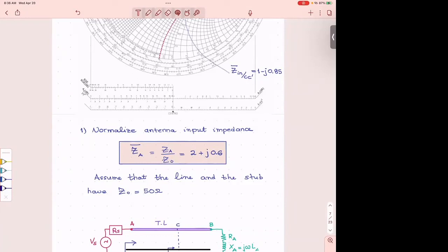Yes. When designing, is there generally a good number? Yes. It's kind of a starting point. 50 ohms is a good start. Yes, 50 ohms for most lines. There are specific line architectures where maybe 50 ohms is difficult to make, so you're looking at 80 ohms maybe, but you will know from your design architecture. All right, but 50 ohms for us is what we are going to use as the standard. So the standard here is 50 ohms, for example. Okay.